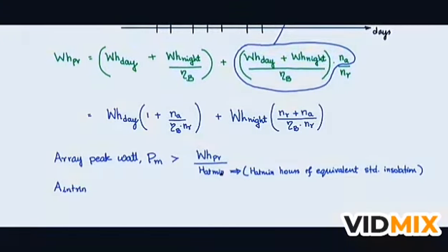And then we calculate the intrinsic area of the PV panel, which is PM by efficiency of the panel. And the actual real estate area, which includes even the walking area, the walkways and the service area, maintenance area, will be 1.3 times the intrinsic area.